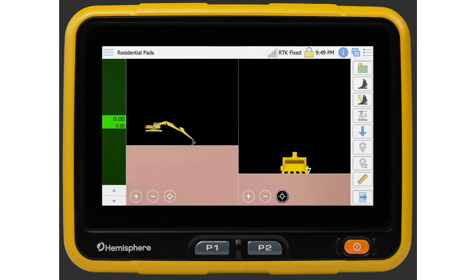If you have finished the cut in front of you and need to track the machine back, you would first have to place the bucket down on a known area that can be referenced after you track the machine so that any elevation change created while moving will be zeroed out.